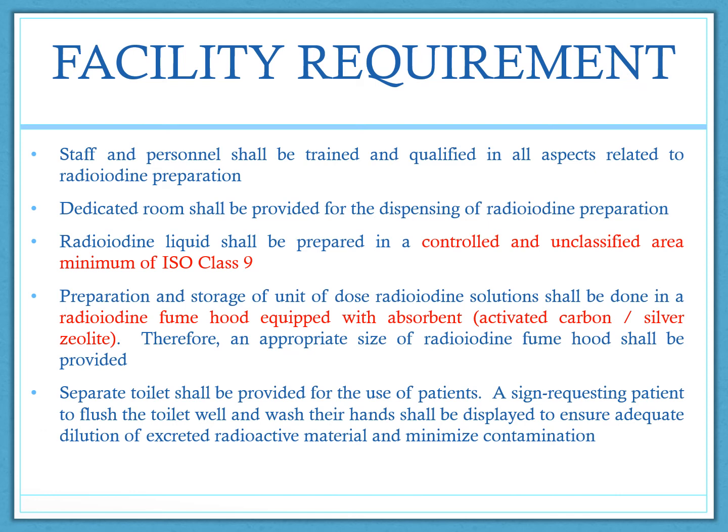And then obviously preparation of radioiodine needs to be done in the radioiodine fume hood equipped with the absorbent, either activated carbon or silver zeolite. And then obviously separate toilet shall be provided for the use of patient, because we just don't want to have a very high radiation background level when the same user is using the same area.